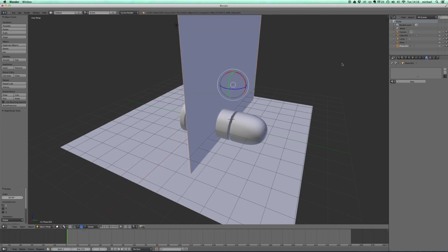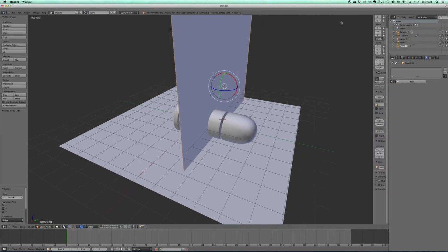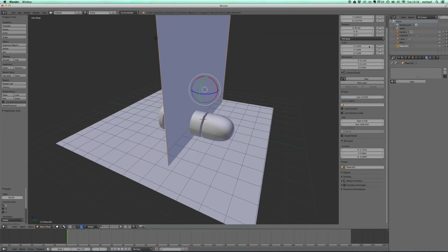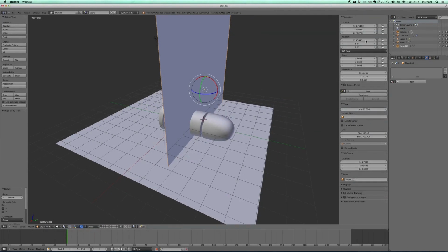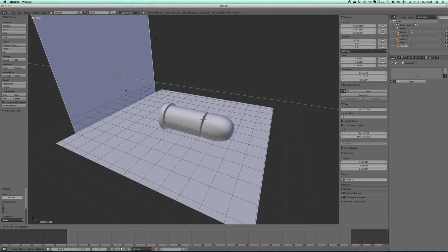To roughly 90. If you want to check it, you can press this little arrow key up here, and what that will do is you can go into the rotation, and I was 0.49 off. That's pretty good, I think, considering I was doing it by guesswork. And so now I have a 90-degree wall. I'm going to put it into position kind of here. That will do.